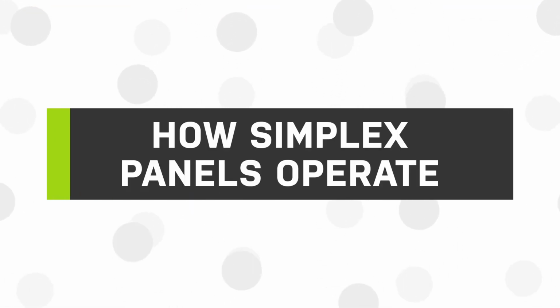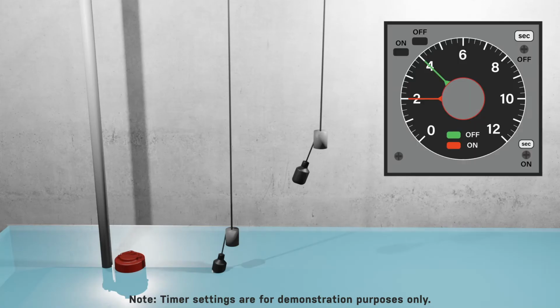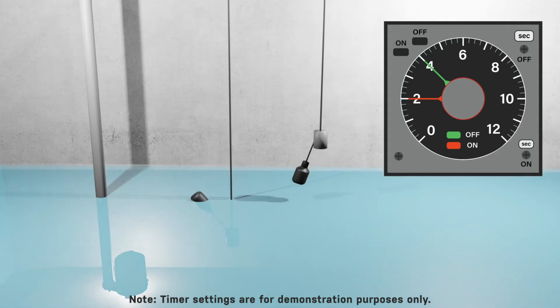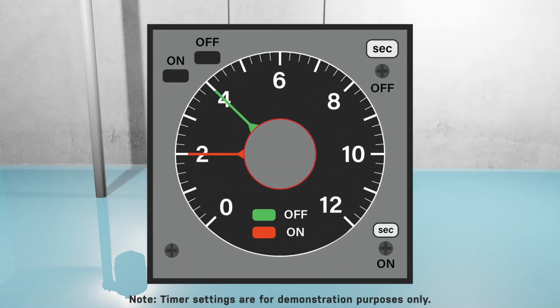How Simplex time dose panels operate. Simplex time dose panels typically control one pump using two control floats: timer enable low level cutout and alarm. When the water rises in the pumping chamber and lifts the timer enable low level cutout float, the control panel calls the dosing schedule to start. The dosing schedule always starts off with the off cycle.